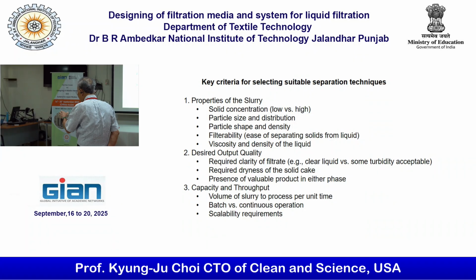If it's high, then skip the next step, something like this. Then the particle size and distribution, particle shape and density, filterability. Is it easy to separate the solid from the liquid? What about viscosity and density of the liquid?